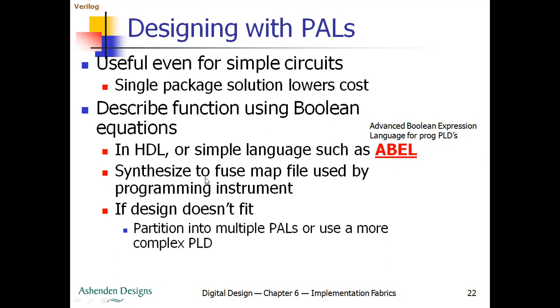You can have the synthesis to a fuse map file used by the programming instrument, and using that instrument I can program these PALs. If the design is large and does not fit in a single PAL, I can partition it into multiple PALs, or I can use more complex PLDs.